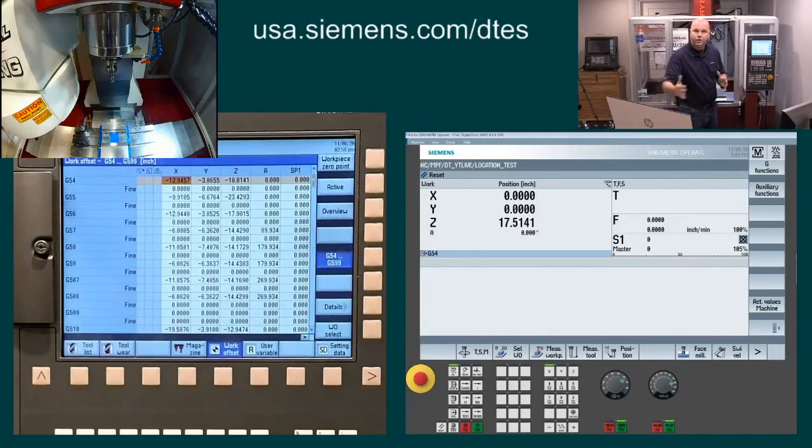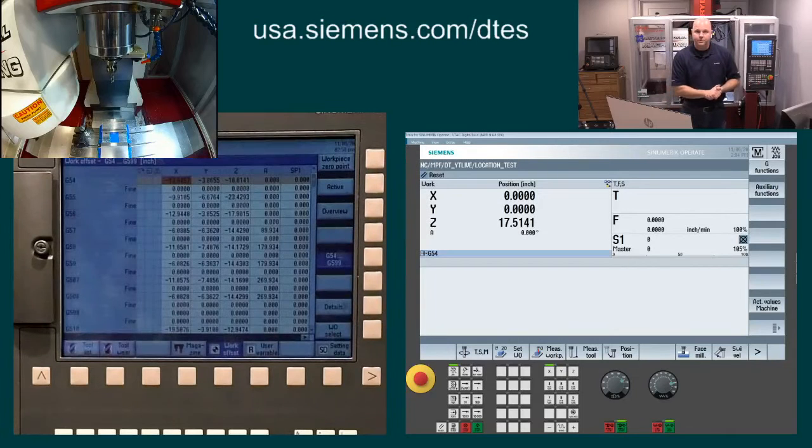However, there could be a disconnect here, depending on the configuration of the machine I pick. And this is where we get into the whole digital twin concept. The machine you're looking at in front of you on the right side of your screen is a duplicate of this machine, built from an archive file that was pulled out of my machine tool and imported into Sinutrain. What that's doing is bringing over all of the machine parameters, everything that this machine knows and is exactly set up for at the moment in time when that file was created, and it will now get duplicated over in Sinutrain.